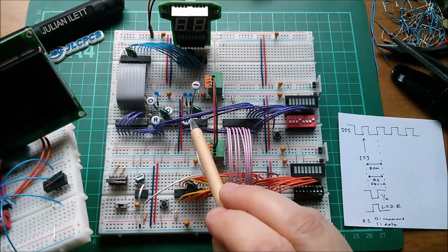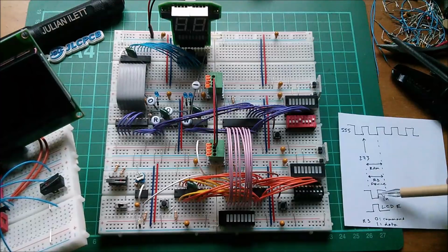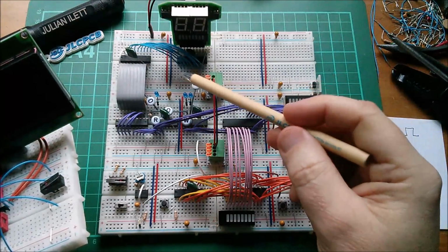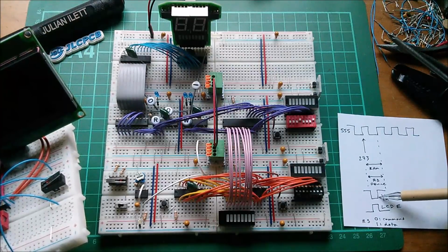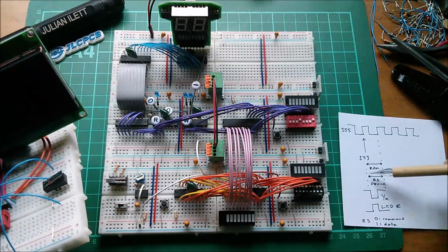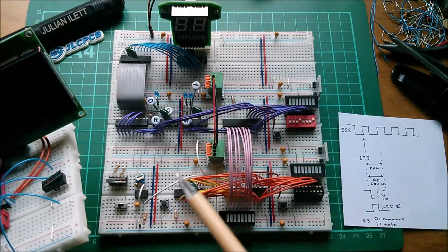And what this effectively produces is a negative going pulse, the rising edge of which is what triggers the latches on here. And the reason for that is that they need to trigger at the halfway point where data is stable in the rest of the system.